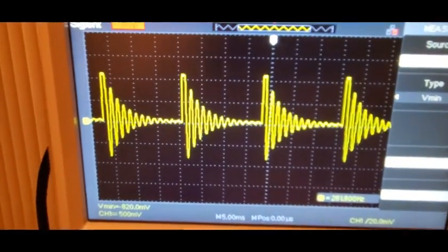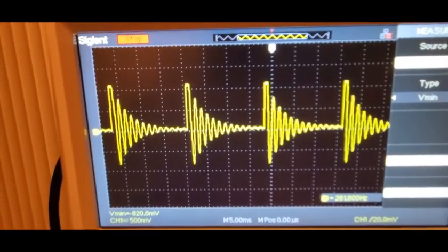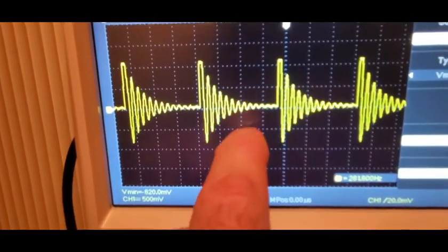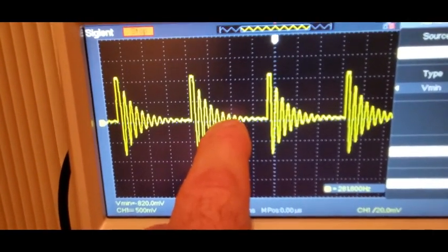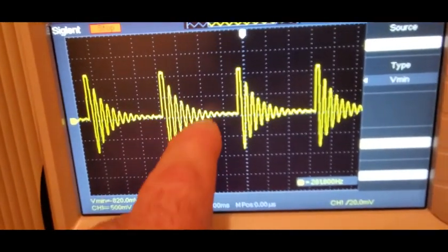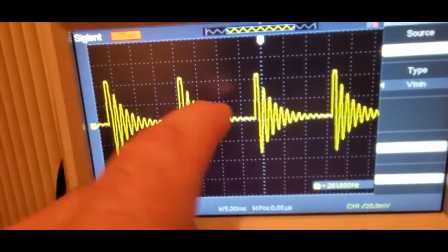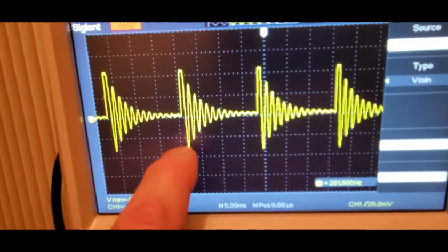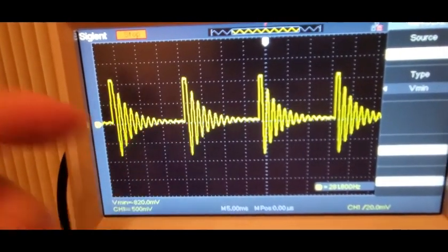So we could go a bit smaller with the caps with this coil, but we'll go to a different coil. But this is that cap and coil ringing 12 times. Now you remember the last one, you basically couldn't see anything from there. So this is a bit less damped, isn't it? And we noticed that also because instead of going to negative 7.2, it went to negative 8.2 or something like that. I'd have to check exactly what we said. But you can see it's less damped this way as well.